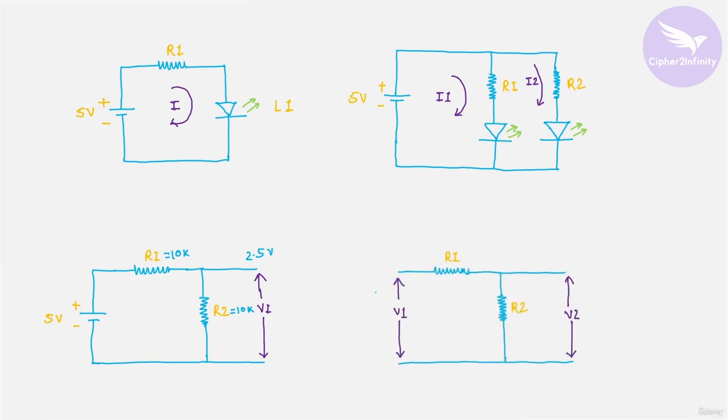Now let's consider one more circuit, which is similar to this circuit. Let's say there is one 5 volt device, and this device is generating a square wave whose amplitude is 5 volts. So this is 0 volts and this is 5 volts. There is another circuit on the output side, and this circuit works on 3.3 volts. If we provide 5 volts directly to the 3.3 volt circuit, it will get damaged. So with the help of a resistor combination, by dropping the appropriate voltage across the resistors, we can achieve 3.3 volts on the output side.